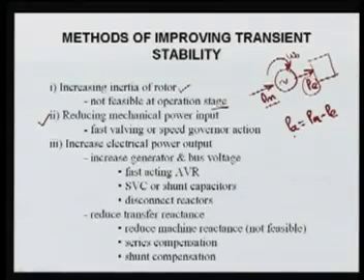So this value will be positive, and this will cause acceleration of the machine, and thereby it will increase the internal angle of the machine, and if it keeps on increasing, it may even lose synchronism.